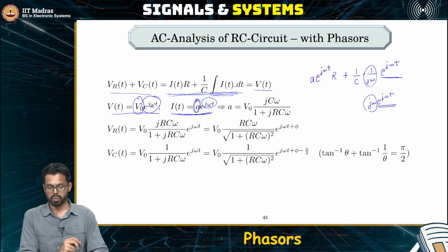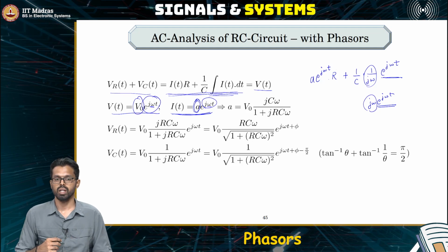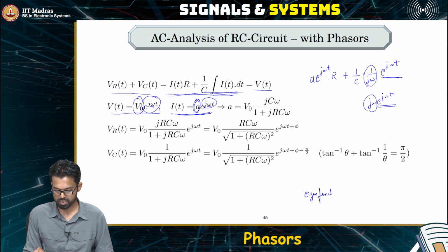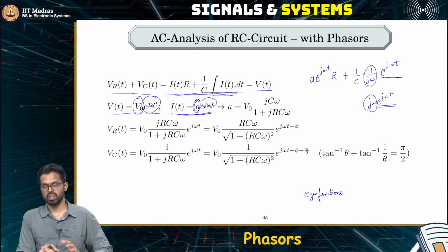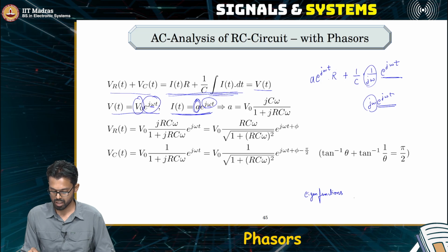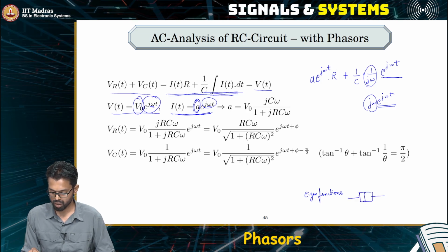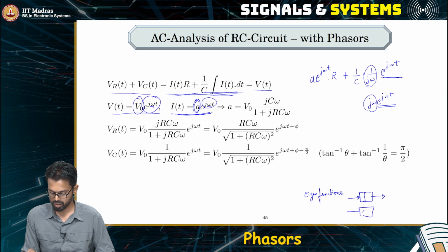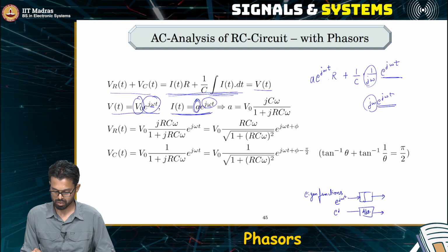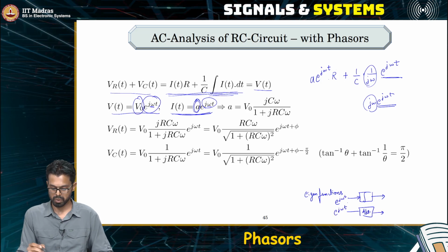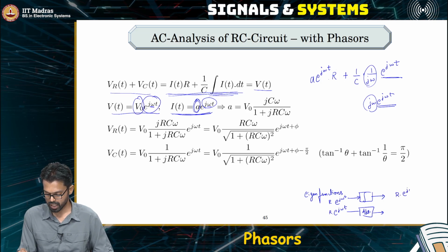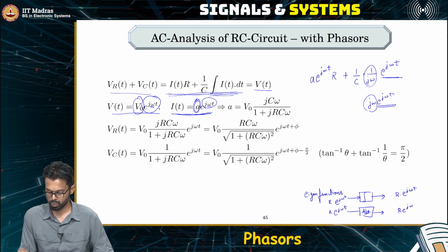So this is a very nice property of phasors. They are what are called eigenfunctions of, this is a terminology, forget it if it sounds too fancy, but what it simply means is that you have an integral block or a derivative block, you pass a phasor through it, it can be whatever magnitude, what you get at the output is exactly the same phasor with a scaling factor,